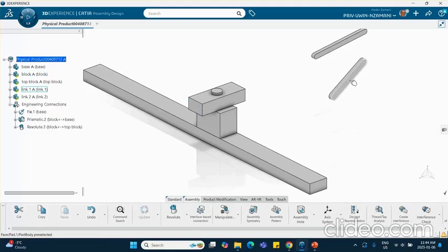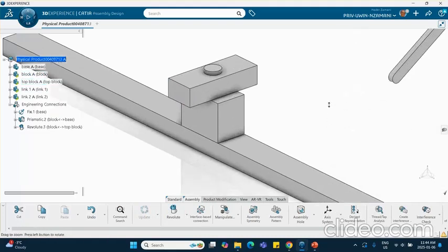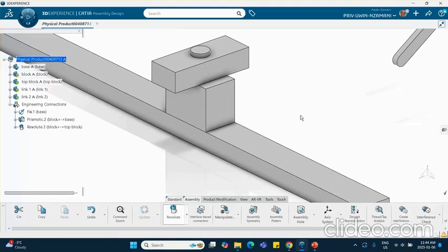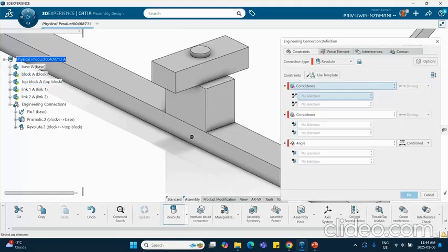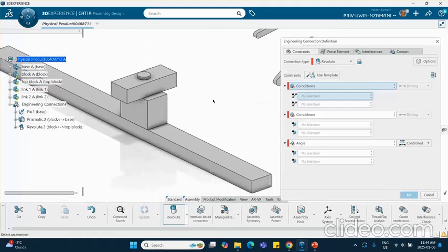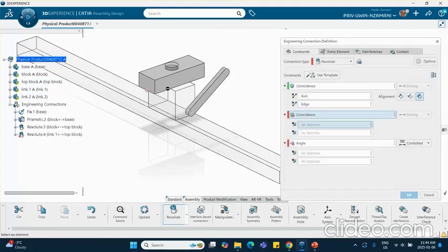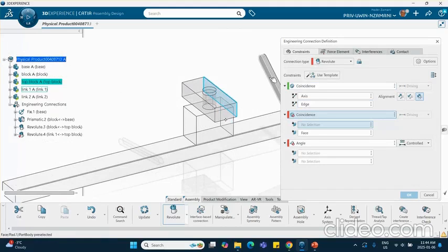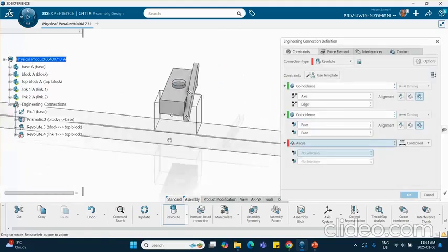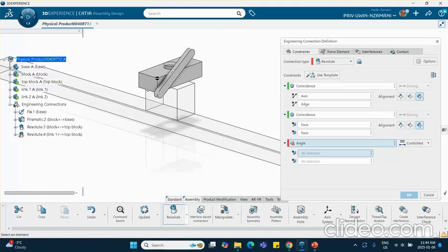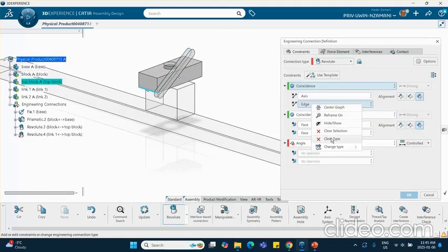Then I'm going to mount this link on that as a revolute. So it's going to be another revolute. I'm going to select, once again, this 4th one. So I use this axis and that axis. Okay. And I use this plane and that plane. Okay. Well, actually, I just noticed that I would have liked to pick the top one. So actually, let me see for a second. This axis and that axis. Okay, let me clear the selection, and use instead that axis.